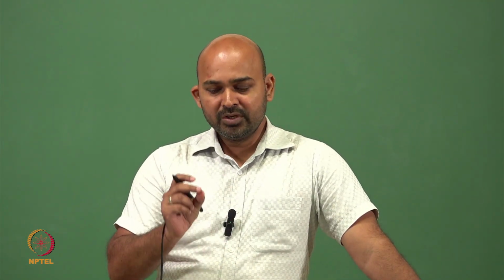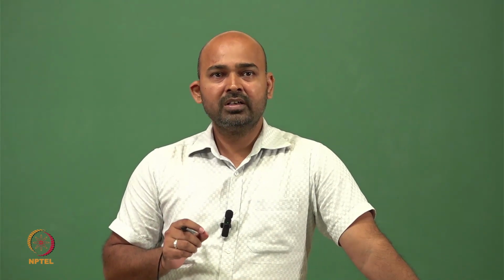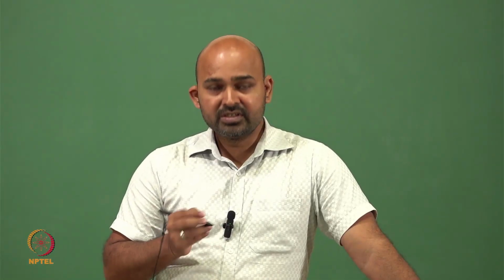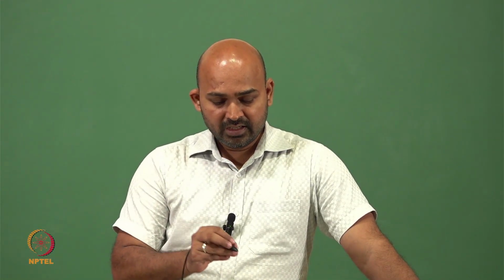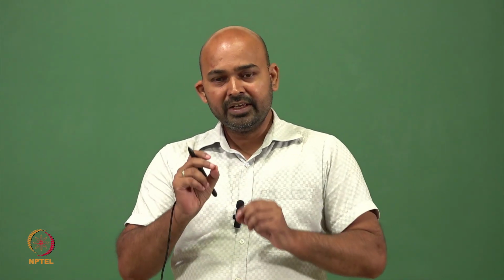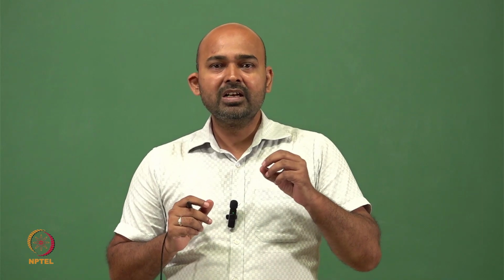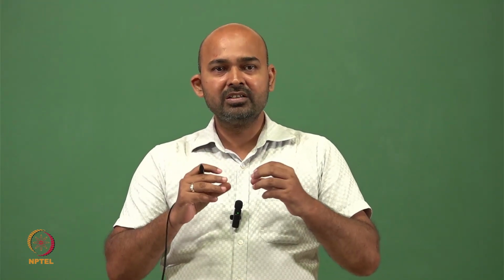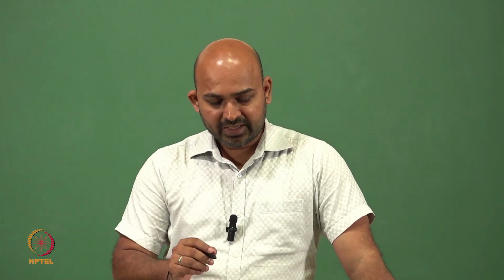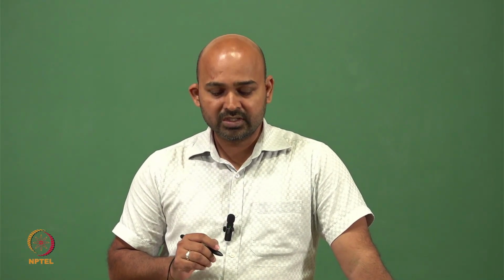They can be easily modulated because the size of these LEDs are very small and junction capacitance is also very less. So we can modulate or we can turn them on and off at very high speeds, which is desirable to send these optical signals. And we can couple enough output power from these LEDs because the area where the light is being emitted is very small, so we can easily couple that to optical fiber efficiently, so that all the photons which are generated by LED, they couple to the fiber and they go inside the fiber. So these are some characteristics of LED as an optical source.